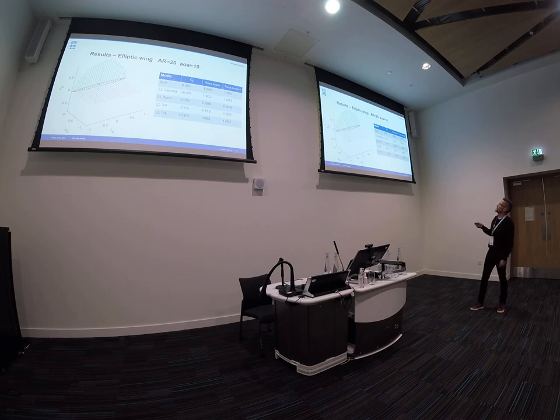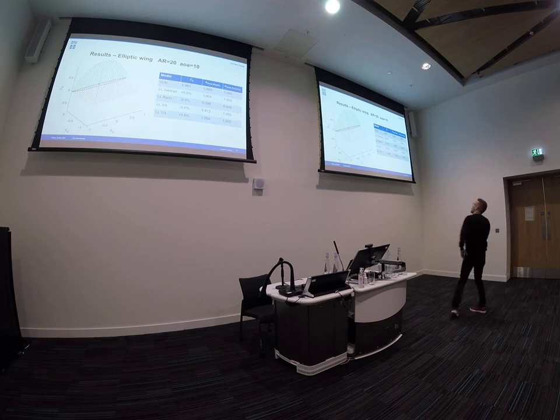This is a straight elliptic wing, aspect ratio high, standard angle of attack. That's the Oswald efficiency for an elliptic wing of high aspect ratio. The analytical solution of that gives 1. So it looks like it's implemented more or less correct. And the high aspect ratio case, we get the same numbers here for almost everything over here.